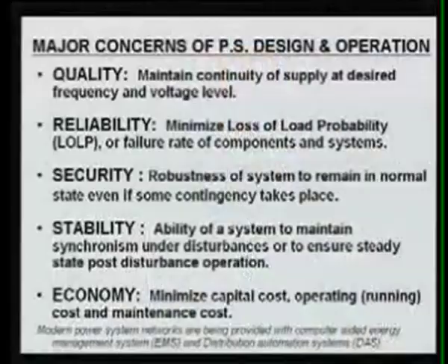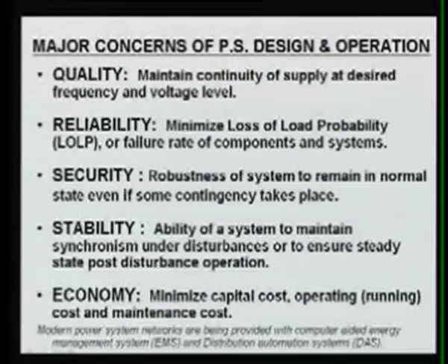Modern power system networks are being provided with a computer-aided energy management system, normally known as EMS. The energy management system is related to your supply side, where we have to operate our generating stations in such a fashion that the cost of production is as minimum as possible. Similarly, on the distribution side, we can also operate our distribution system in an automatic way so that we can minimize faults, minimize losses, and finally give better service to our customers. That is one of the main mottos of the whole electricity business.